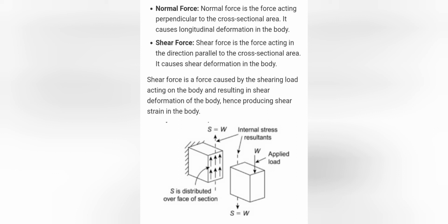Going back to our floor slabs and column illustrations, the two-way punching shear failure can be avoided either by providing stirrup reinforcement or shear strips or by increasing the depth of the slab under the column, also called column drop. Similarly, the two-way punching shear failure in an isolated footing can be avoided by providing shear reinforcement or increasing the depth of the footing.